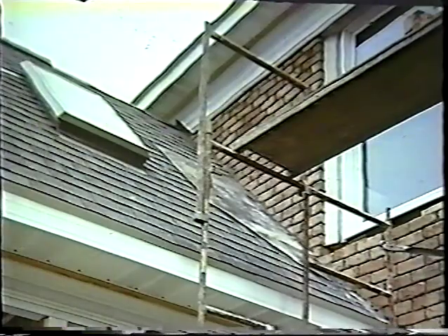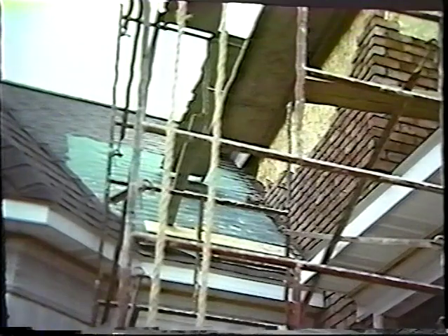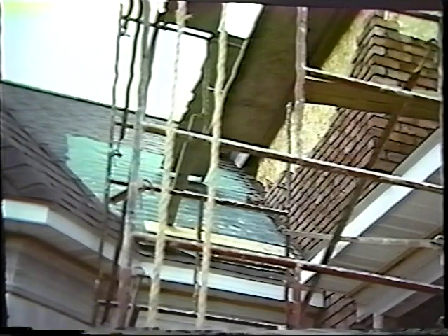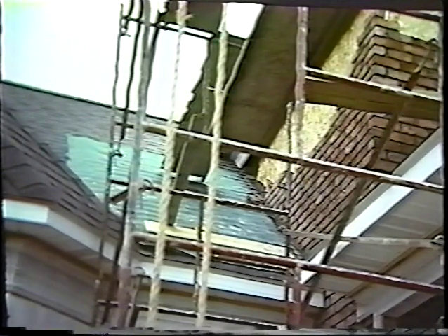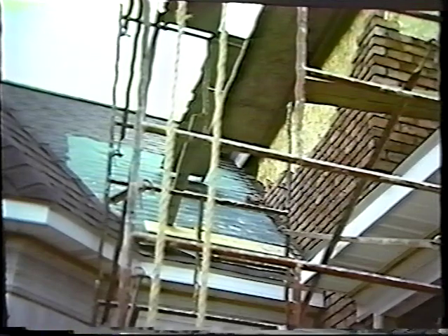The best way to solve this problem is by continuing the end wall down to a foundation or footing. If the opening is short enough, a steel angle can be used to support the brickwork over the roof or opening. In some cases, the choice is to support the brick veneer on the roof's framing members. While this can be done, it may conflict with the local building codes. This alternate means of support must be approved by the local building official.